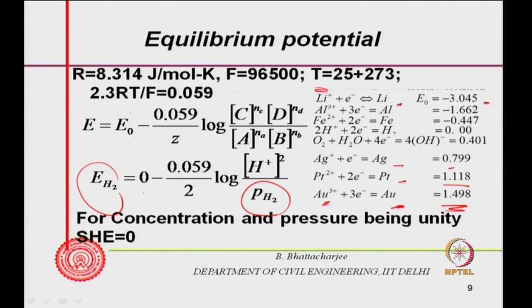So noble metals have positive electrode potentials and do not form an anode. The dissolution reaction does not take place readily there, while in the case of other metals such as Fe, this reaction would occur and it would act as anode. So if you connect Fe with gold, Fe will automatically become the anode and gold will be the cathode.